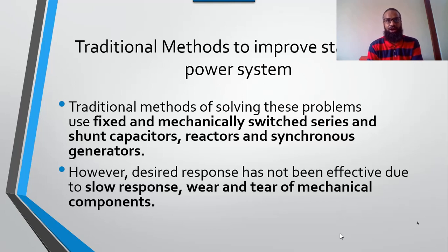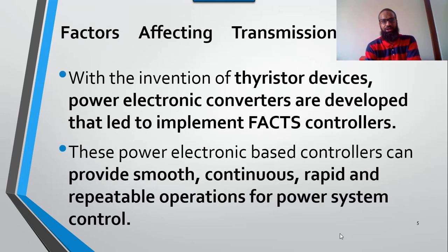Similarly, they are mechanical switches, so their wear and tear is very high, and their maintenance is very costly. They are also relay based. The switching time of the relay is comparatively very large, and it produces delays. So these faults may damage our load or the transmission or the generation side of the transmission.